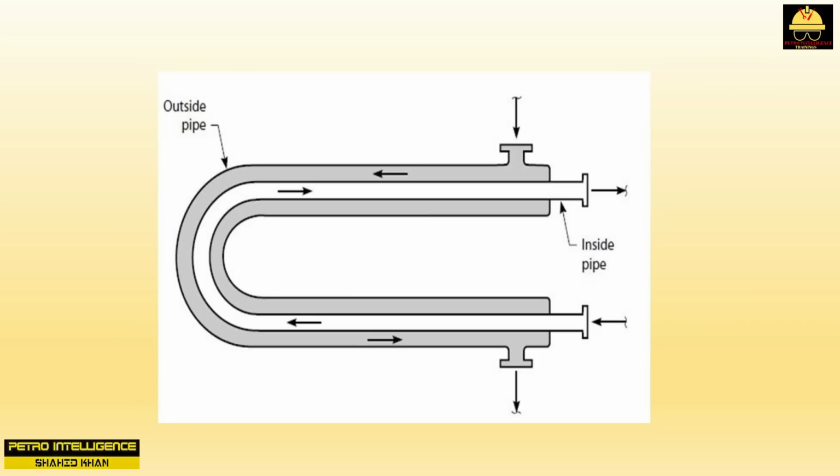A single pipe or tube simply cannot have much area, typically 100 to 300 square feet. Exchangers of less than a few hundred square feet can be economically designed in a hairpin configuration. Larger exchangers are, for economic factors, shell and tube types.